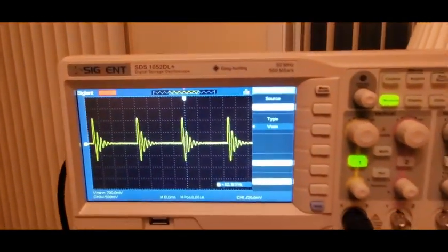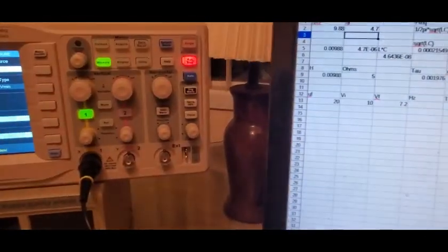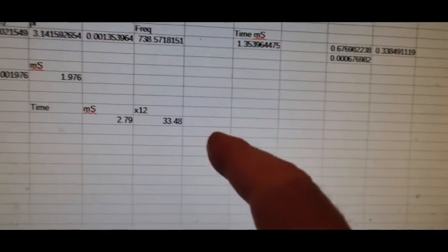Now, one of the glories of this thing, when we look at our code, is that it's calculated at around 677 microseconds where the thing goes most negative. But the cap might be 4.6, and the measurement might be off a little bit. Doesn't matter now. All you have to do is, let's set this at 750.